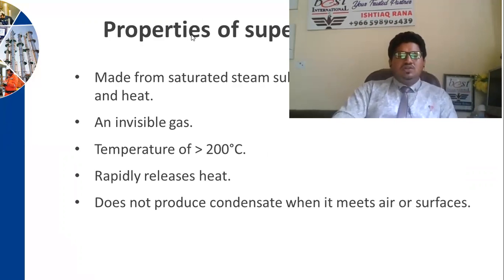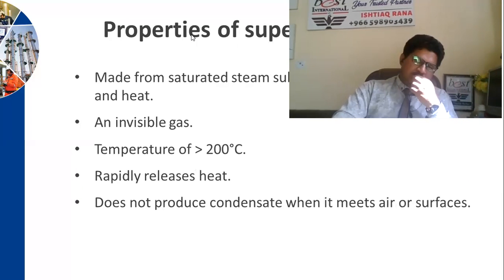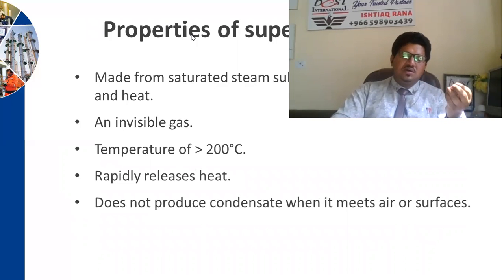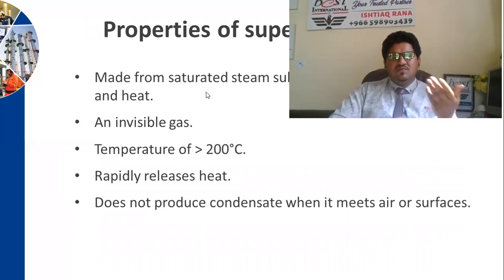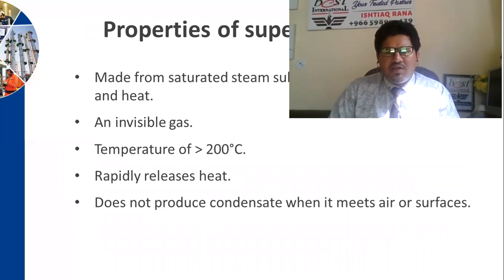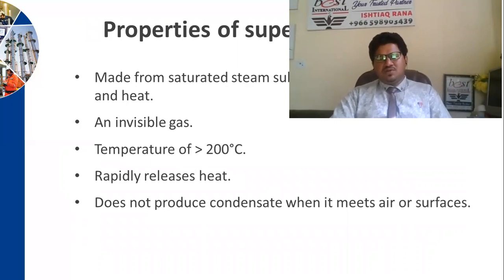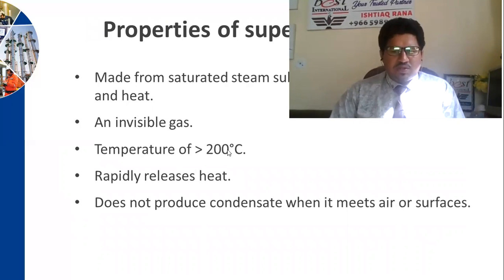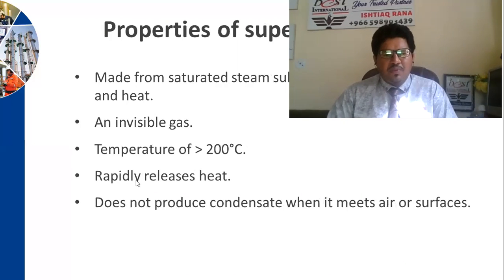Now, this steaming process. I hope the people who are working as a reliability engineer, or as a CSE supervisor, or even as a process engineer, can understand what I'm talking about. This steaming process can be saturated steam and even superheated steam, made from saturated steam subjected to further pressure, an invisible gas with temperature that could be more than 200 degrees.